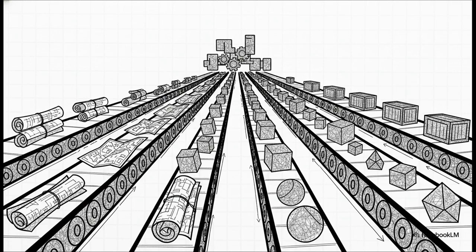In fact, to actually make this work seamlessly, there are 4 parallel highways running through this chip. The program bus and the program address bus handle the instruction side of things, delivering the code itself and the addresses for that code. Meanwhile, the data read bus and the data read address bus are totally 100% dedicated to moving the actual data. Having these 4 buses allows the processor to grab an instruction and read an operand at the exact same moment without any collisions. It really is a logistical masterpiece.